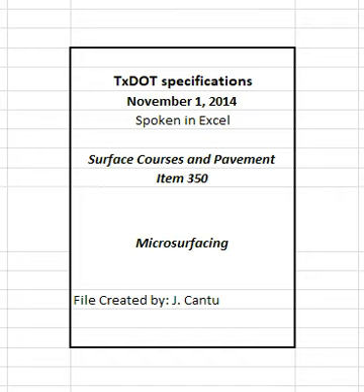4.11 Workmanship. Immediately take corrective action if microsurfacing material is exhibiting evidence of poor workmanship, delayed opening to traffic, or surface irregularities, including excessive scratch marks, drag marks, tears, streaks, raveling, delamination, and segregation. The engineer may allow placement to continue for no more than 1 day of production while taking appropriate action. Suspend paving if the problem still exists after 1 day until the problem is corrected to the satisfaction of the engineer.